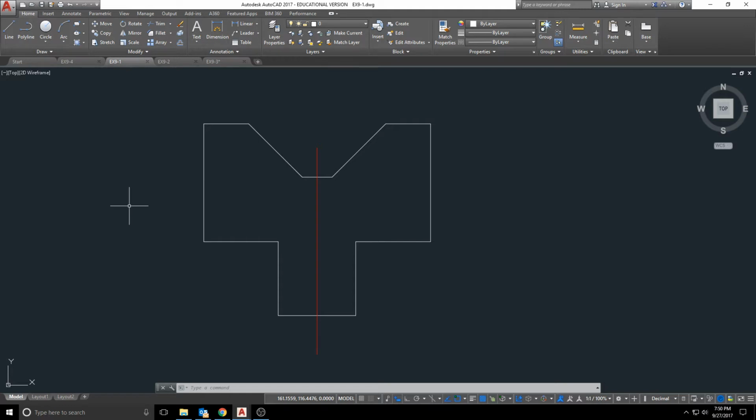But when the person actually constructs it and mills it, or whatever machining process they use to create it, the chances of them getting exactly 38 millimeters is pretty slim, especially once you start getting down into 2 and 3 decimal places. There's going to be some variance because of tool wear or just any other types of reasons that could exist for the variances.